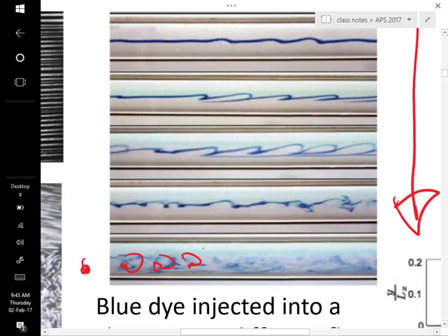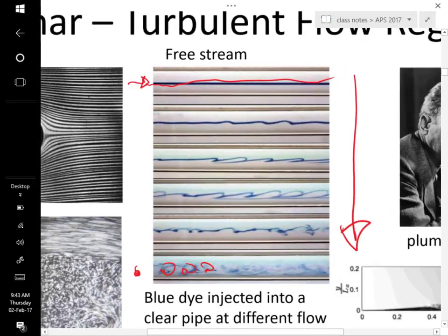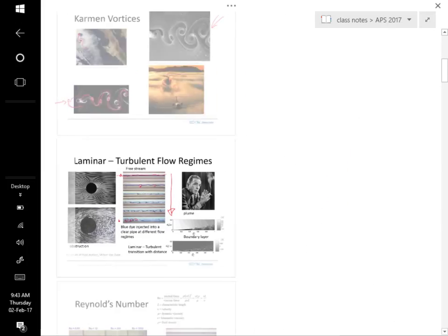And then in between, we've got this kind of a transition pattern where the flow is perturbed, and we might imagine there's like a vortex in here, but they're just kind of scattered through the flow. So it's not really down here, we've got the entire flow has these vortices through it at a range of scales, but here in this transition region, the vortices are forming, and then perhaps they form and die out, but they're kind of scattered through the flow in this transition regime.